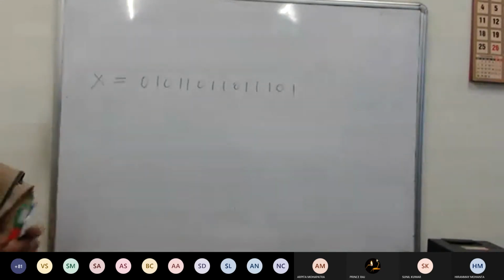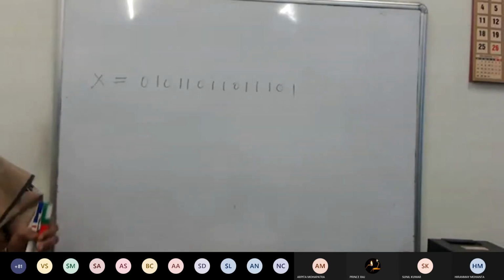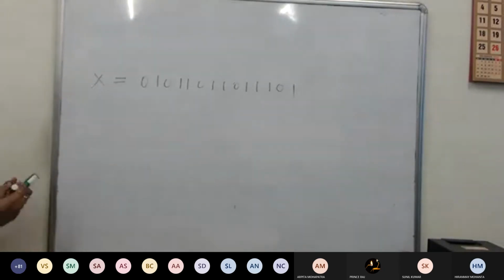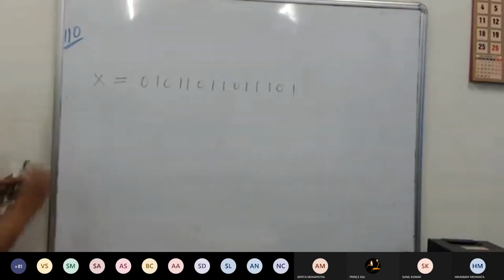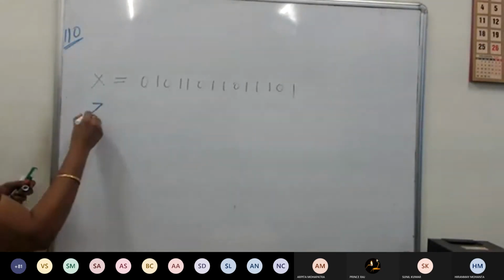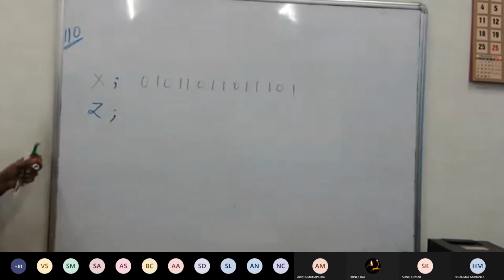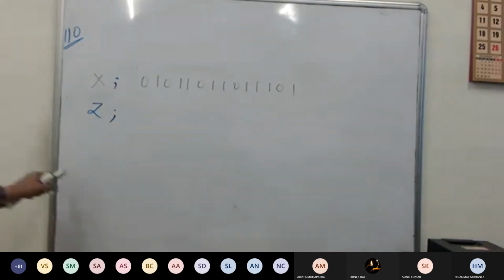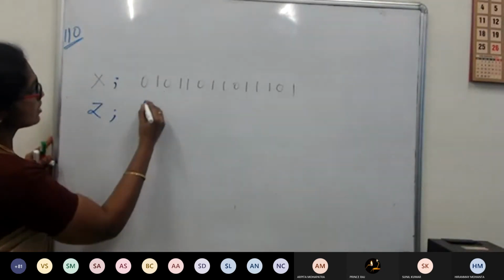The sequence detector is programmed, I can use the word program, to detect 110. Carefully understand. So my sequence is 110 to be detected. My output Z has to show 1 after detecting that. So now no need of a timing diagram, I can give it here itself right now. Our target is 110, so I will write this sequence.